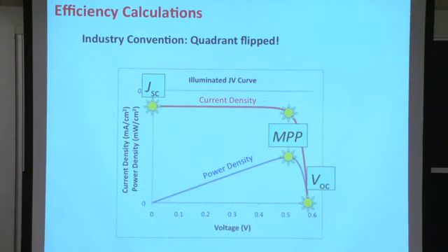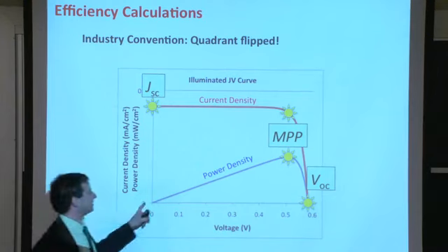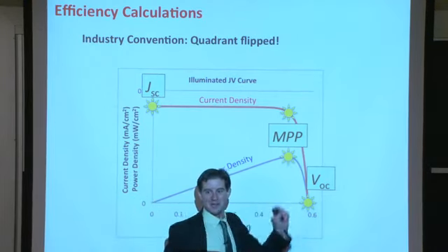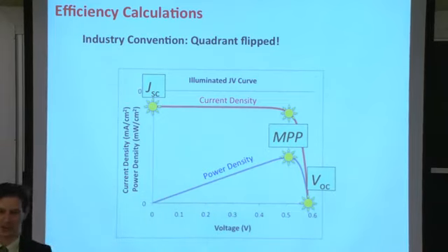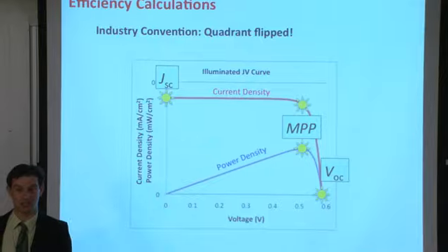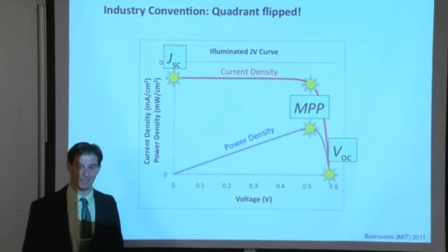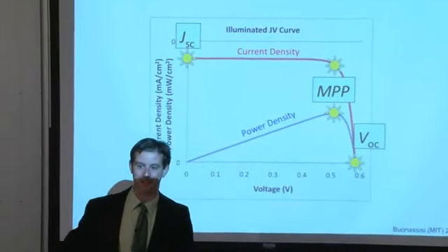Ensure that the device is working at the maximum power point, does an external voltage have to be applied to it? So to ensure that the solar cell device is operating right here, a couple of things need to happen. You need to have the right illumination conditions, and you need to have the right load. So the two need to be matched to each other. Absolutely. And that's where some of the power electronics come into play.